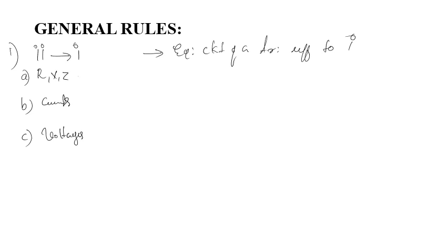If we transfer all the resistance, reactance, and impedance from the secondary side to the primary side, we must divide it by k square. In the first case, R2 is the secondary resistance. When it is converted into primary, it is R2 dash.